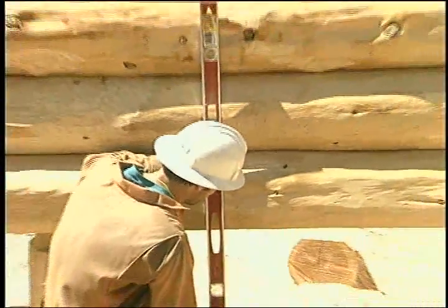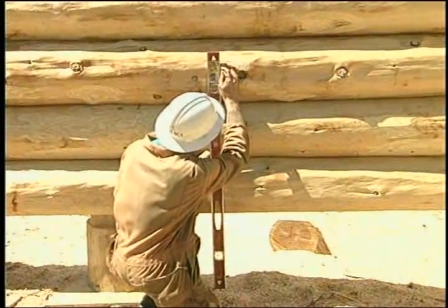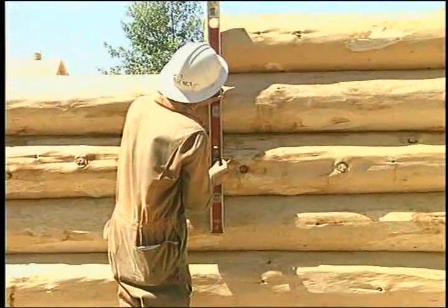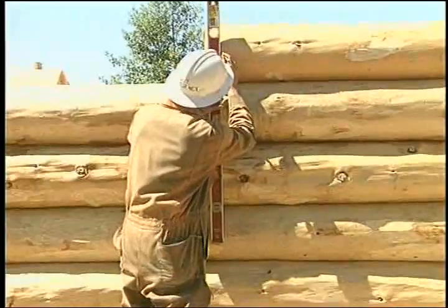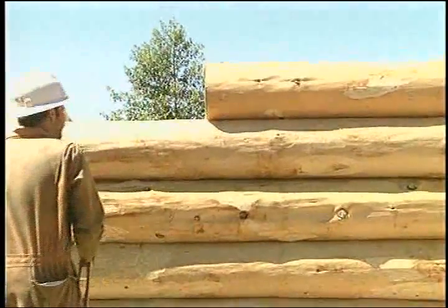We have already dealt with the placement of these logs and the control of the wall height. In addition to the alignment of these logs, it is a good idea to measure the length accurately. This should be 50 millimeters or about 2 inches longer than the final cut for the opening.